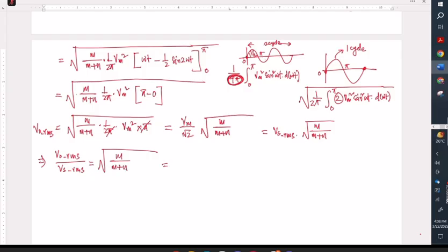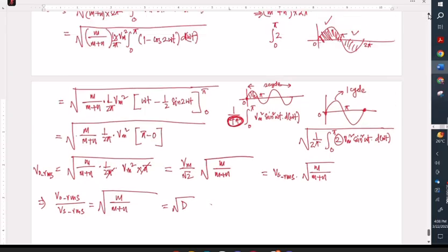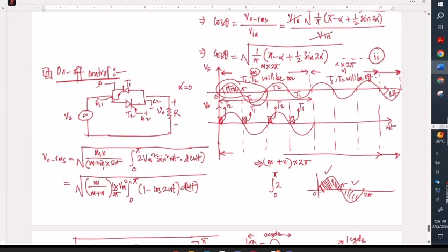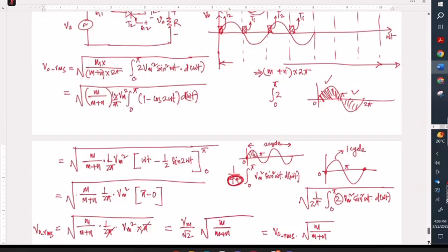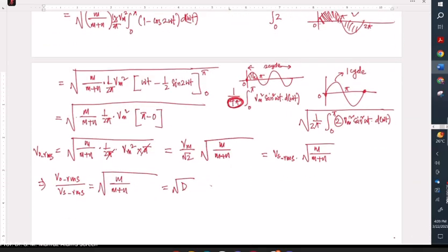So that is also known as the duty cycle, because if we consider the total area to be one cycle, then of which m times is on and the remaining time is off. In that way, we can consider it to be the duty cycle, what we discussed for the DC to DC converter. You got my point, right?